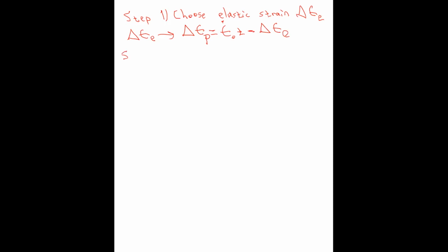Step 2 is to calculate the stress. The incremental stress is proportional to the elastic strain. Plastic strain has nothing to do with it. So we have the stiffness tensor times the increment of this elastic strain, this guy right here.